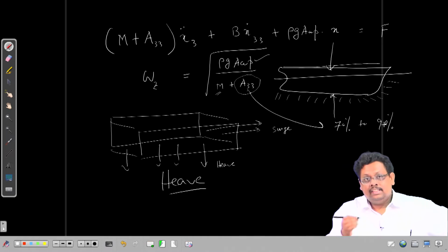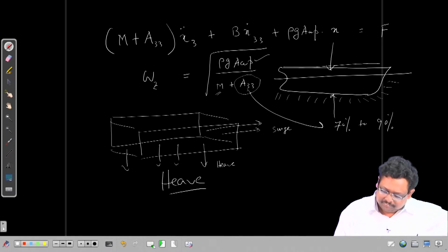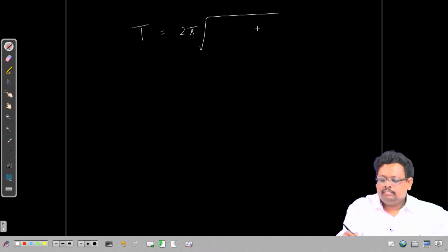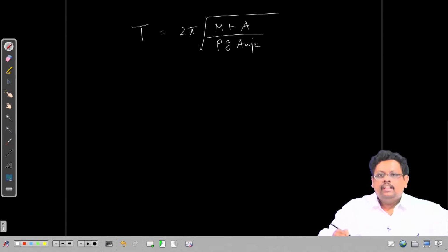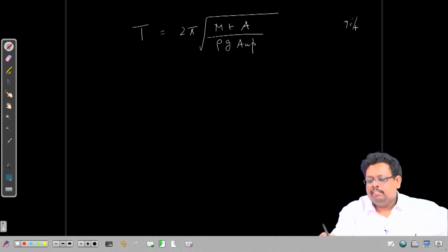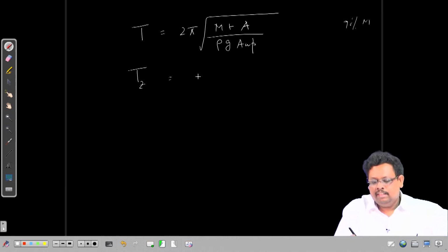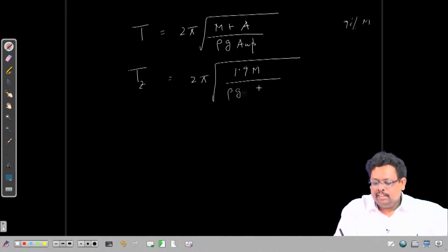Now, let us take another very interesting thing. Let me write the time period, of course, it is 2 pi square root of (m plus added mass A) divided by (rho g into AWP). Now, what I am trying to say is, let us assume that A is some 90% of the mass. Okay. Then I can redefine this, and I can call T z the time period in heave, which is 2 pi square root of 1.9 into m divided by rho g into AWP.